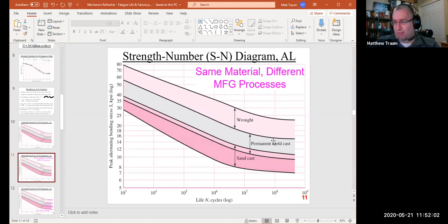If you ever played with Hot Wheels cars when you were young, those little die cast toy cars, that's a die casting process. You basically have a metal mold material that has a much higher melting point than aluminum, and you squeeze liquid aluminum into this mold, the aluminum takes the shape of the mold, and then you open up the mold and pull out your finished aluminum part. So that's a permanent mold cast process, which happens under pressure.